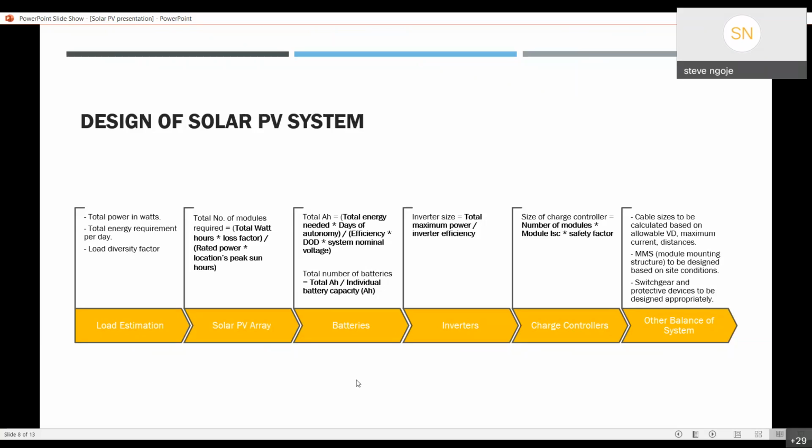For example, for most lead acid 12 volt 200 Ah batteries, you'll see something like 700 life cycles. 700 life cycles just means you've charged and discharged this battery 700 times. If you charge and discharge daily, that's roughly just over 2 years, and then after that you will need to change the battery.